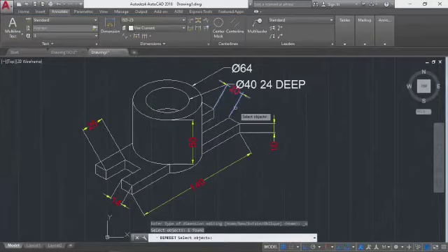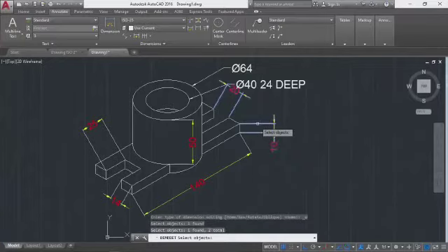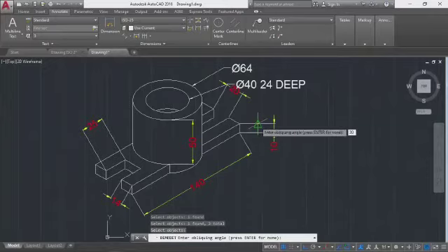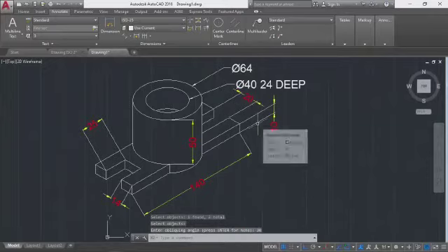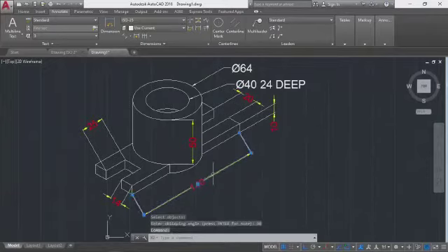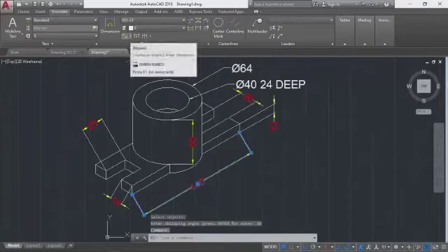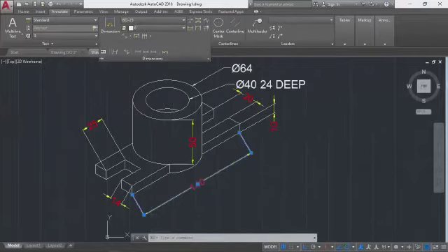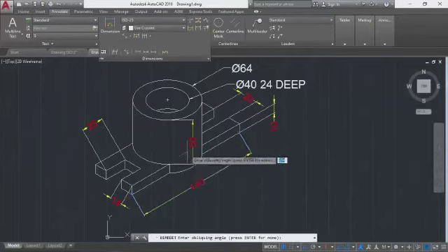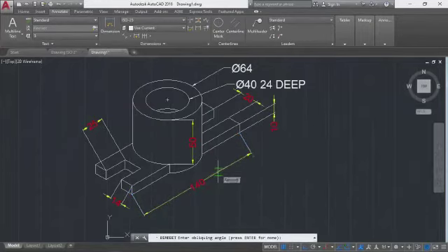Now oblique, you click on this. You can specify, select the object. You've selected the object. And press enter. Say specify. You can specify the angle, the direction, 30. Do you see that? So it will not be touching. For this, you click on it. You click oblique. Select the object. Says okay. You press 150. That's the direction.